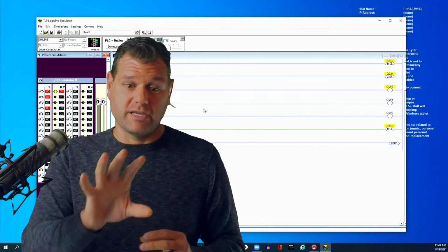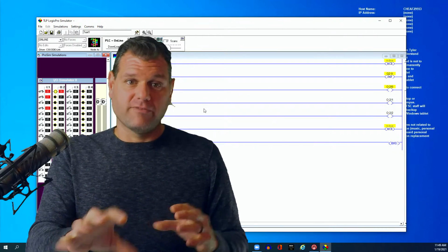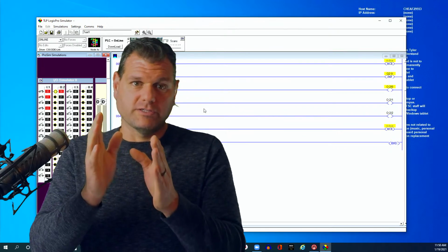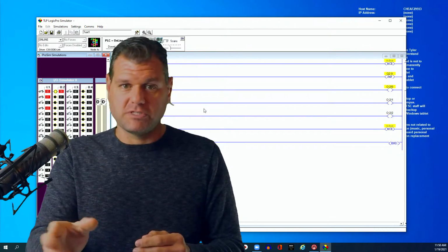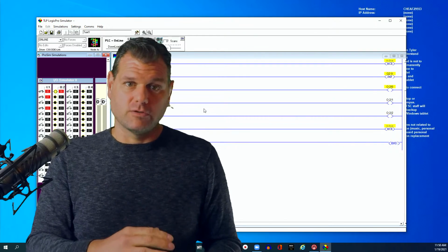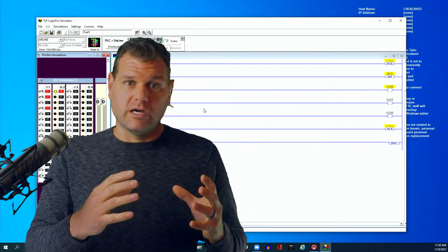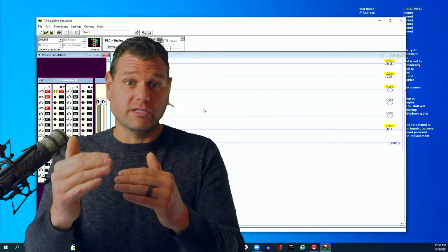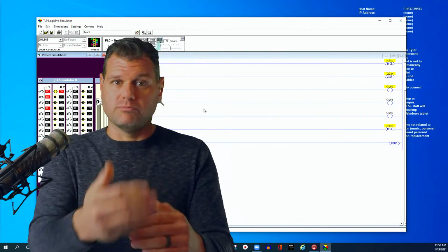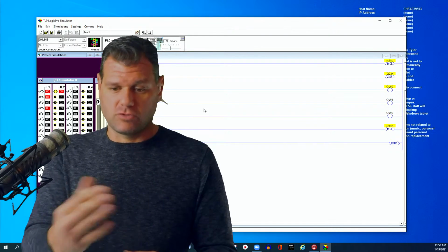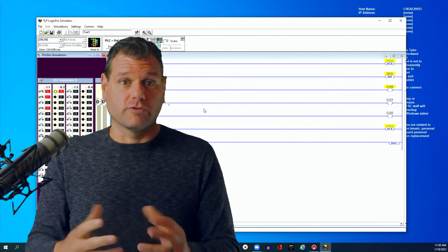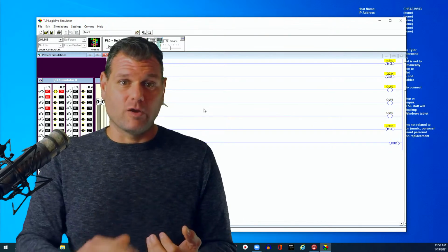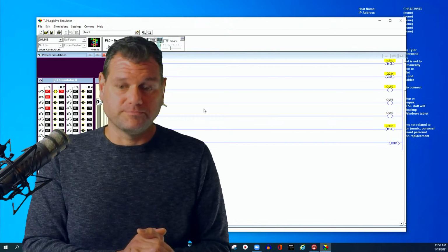So that's one of the beauties, because you're only doing the heating stuff when you're below temperature. So let's say you have two conditions. One is tank full, one is you're below temperature. When that happens, it jumps to the subroutine, it does whatever it needs to do to heat the system up, and then when the temperature is reached, you go over and you make sure everything's shut off. Turn off your gas, turn off all your stuff. You get everything back to its normal state to turn the fire off so you don't keep heating. And then you don't scan that anymore. You don't jump to that subroutine because there's no reason for it.